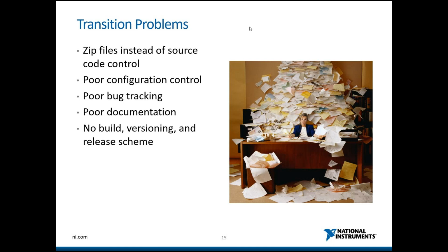Poor configuration control. We had all these circuit board testers, and they had written like a scripting language where you could type in a text document and some commands, and it would run them. But they had no control over them, and people would change them in the field, and then you have 5 machines, and they'd each have a different sequence on it. Nobody knew which one was the correct one. So the configuration control went way beyond just source code control, just configuration control of everything. For example, the circuit board testers, they had issues where they didn't have really good wiring diagrams, and it just said, oh, connect this to ground, and one person connected it directly, and one connected it way around, went around in like 3 circles and plugged it in somewhere else, and it just made troubleshooting really hard.